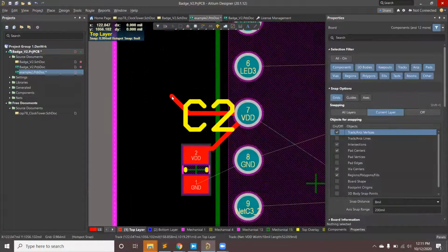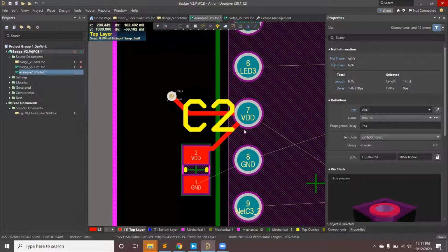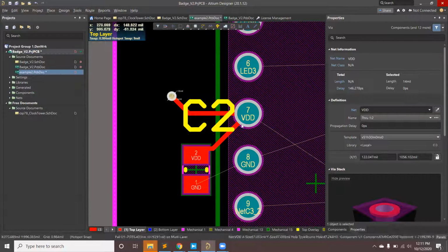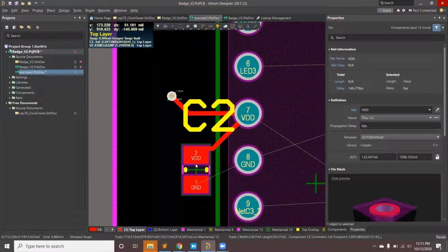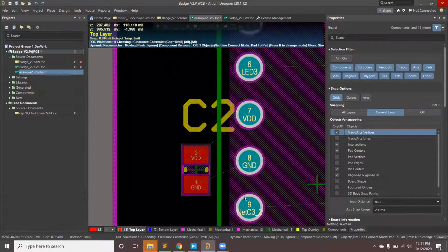And then you place a via. This is what you should not do, because what this will do is it'll pull up from the plane. It will go to the power point, and then it will go to this filter. This is not doing anything. This is not helpful. Don't do this. It's not actually decoupling anything. It's sending a signal right here, and then the signal is going here. Not useful. Don't do that. So yeah, make sure it goes through the capacitor before it goes to the component.